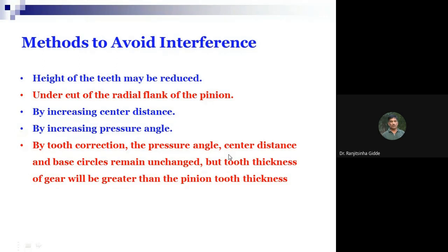But the tooth thickness of the gear will be greater than the pinion tooth thickness. So another way to avoid the interference is just by tooth correction.